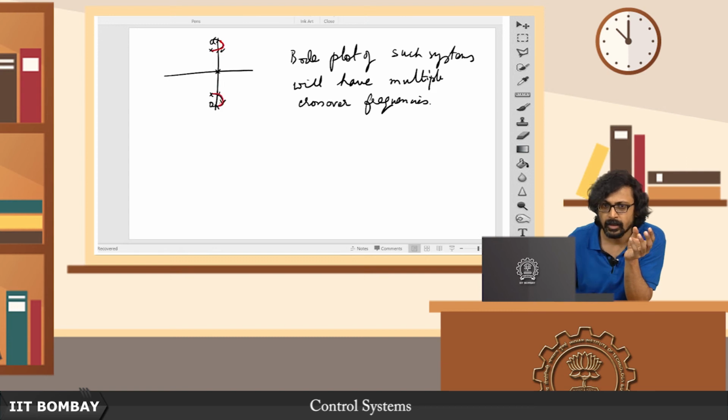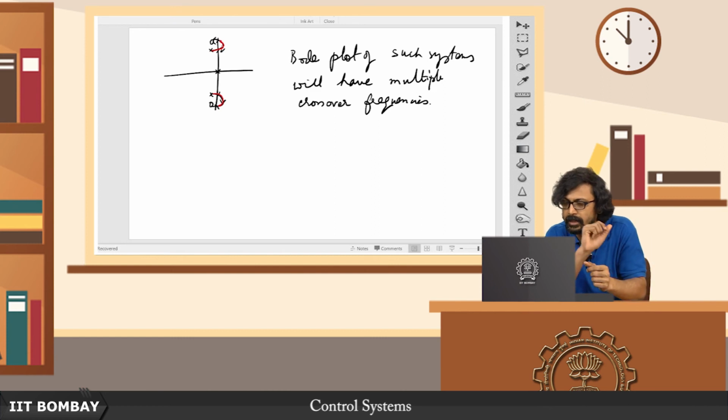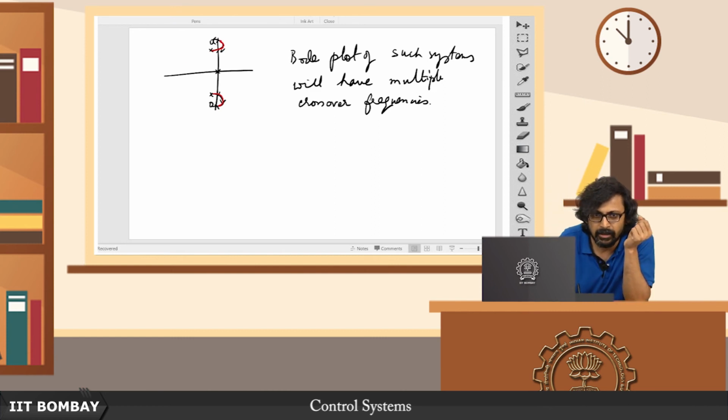At this place. Because you have at the back of your mind this notion that increasing gains is a bad thing, you feel, okay, seems like the system is unstable, what do I do? Let me reduce the gain. You keep reducing gain and go on and on, and at this point when you have arrived, you feel, oh, probably this is not stabilizable at all. On the other hand, if you had been keeping your mind open to the possibility that such a situation has unfolded here, you might have just said, okay, let me try increasing the gain a bit more. So you increase the gain a bit more and voila, you are back in the stable region again.